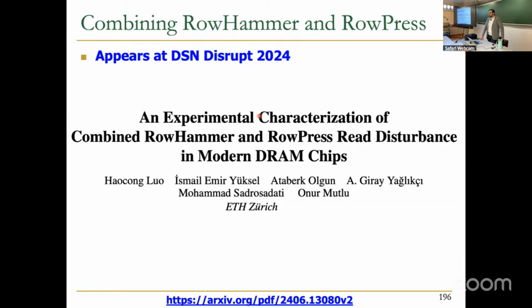So basically, once you apply high voltage, low voltage, or high current, low current, you affect the electrons nearby, right? For the current, I believe it should be something like that. For voltage, it's more like you create an electric field, you attract electrons, and then you release those once you go to low voltage, and electrons move back and forth. While doing that, they get trapped in some holes, and once that happens, they create some weak channels in some leakage paths, so that they exacerbate the leakage that already exists.